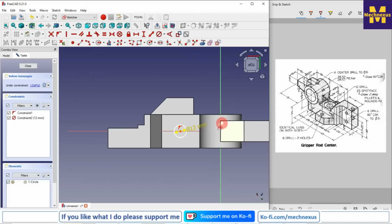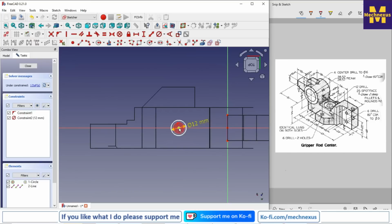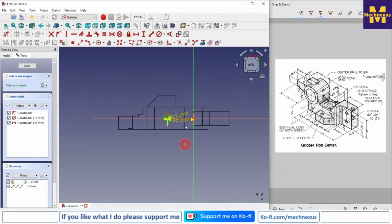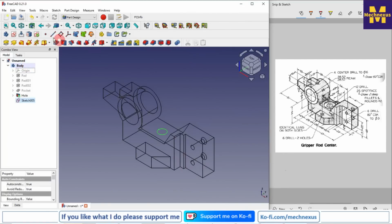So I will click on the project geometry and we will switch to the wireframe, and we will select the hole circle and this edge and give it a dimension of 38. Now come out of the sketch and from here switch to the flat lines.